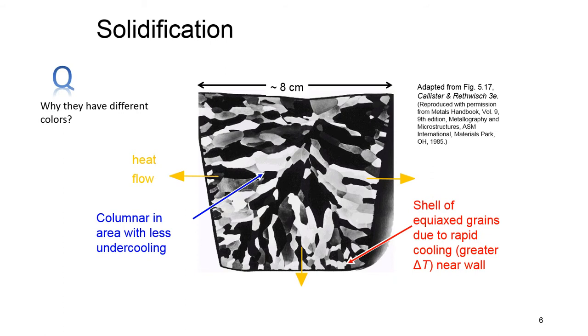The grains that you can see, as an example, if you look at this structure which has been polished, you can see grains can be equiaxed like these ones, which means they don't have a preferred orientation, or they can be columnar like these ones, which are elongated in a certain direction, and these are called elongated grains as well. The equiaxed grains are roughly the same size in all directions, like these ones here.